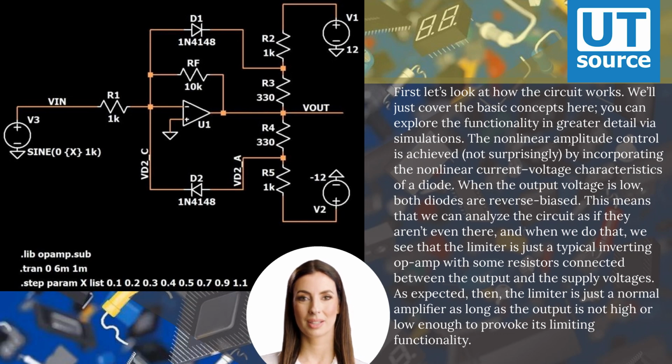When the output voltage is low, both diodes are reverse biased. This means that we can analyze the circuit as if they aren't even there, and when we do that, we see that the limiter is just a typical inverting op-amp with some resistors connected between the output and the supply voltages. As expected, then, the limiter is just a normal amplifier as long as the output is not high or low enough to provoke its limiting functionality.